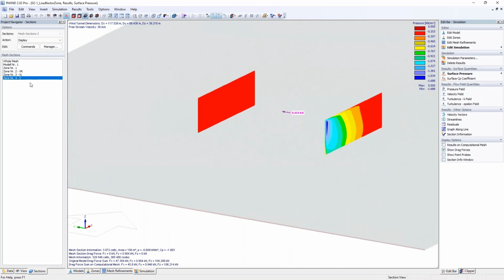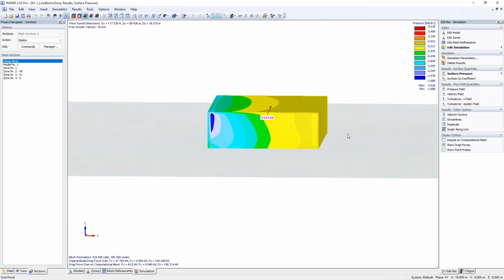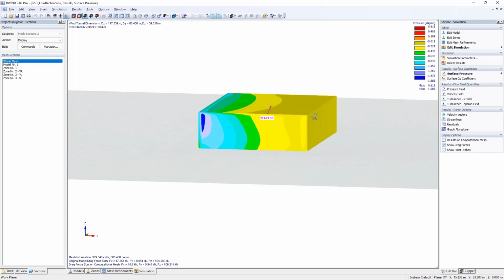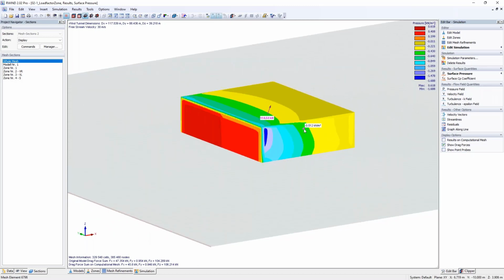And the main focus for this is, imagine that the wind analysis maybe has some weaknesses, because if the steady calculation, or stationary calculation, cannot really capture the suction at the backside of a building, you could just define a zone there and increase the value. Or if you think that you have to add some special safety factor, you can increase it as well. Or if you think it's way over the top, you might decrease it. And then if you hand it over to RFEM 6, the loads will also include the factor. So you do not have to rearrange or multiply them later on in RFEM 6.